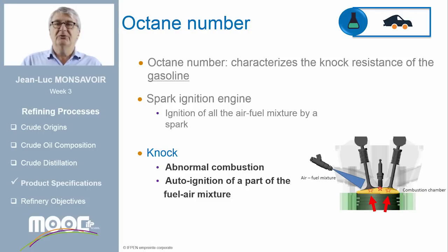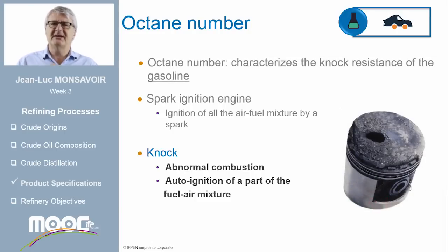It consists of auto-ignition of the fuel at a non-optimum position of the combustion chamber, before the spark. This uncontrolled auto-ignition creates pressure waves which lead to vibrations. This vibration sounds like a metallic noise. It's called knock. The knock phenomenon can induce several engine failures. This picture shows a badly damaged piston that indicates the effects of long-term engine knock.